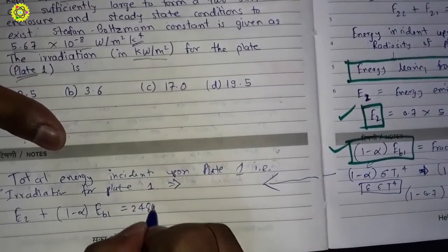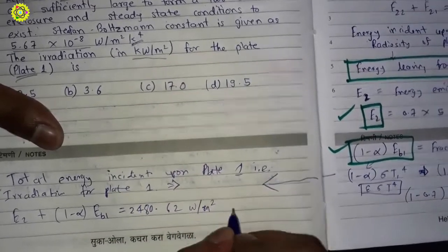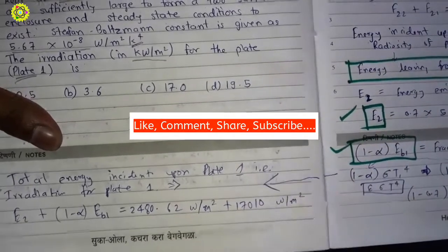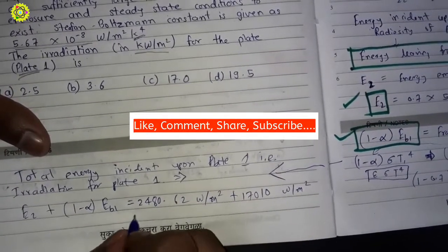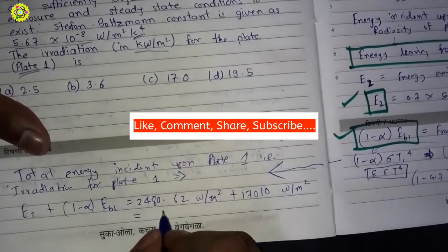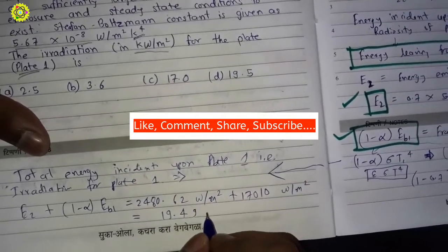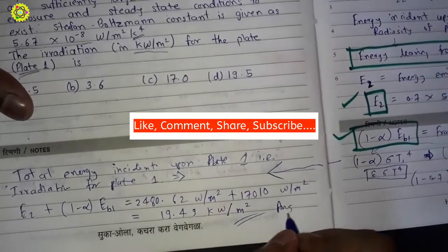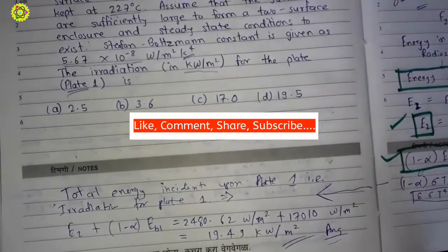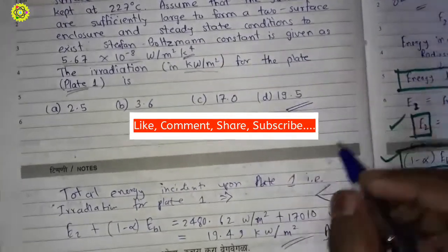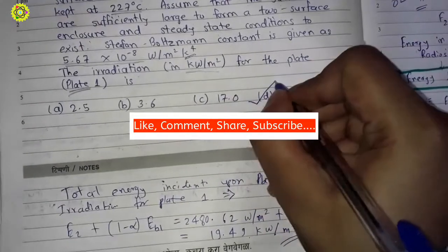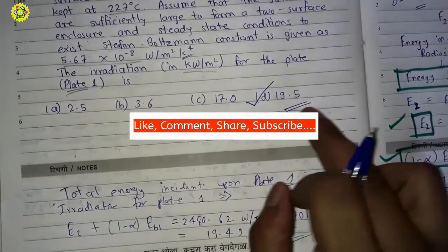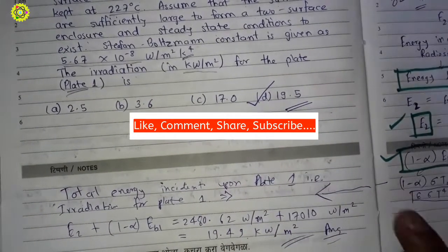2480.62 watt per meter square plus 17010 watt per meter square. So after calculating, we will get the answer 19.49 kilowatt per meter square. So this is our answer for this question, and in the options, as you can see, this is the nearest answer to this question. So option D is the correct answer. The irradiation for plate 1 is 19.5 kilowatt per meter square.